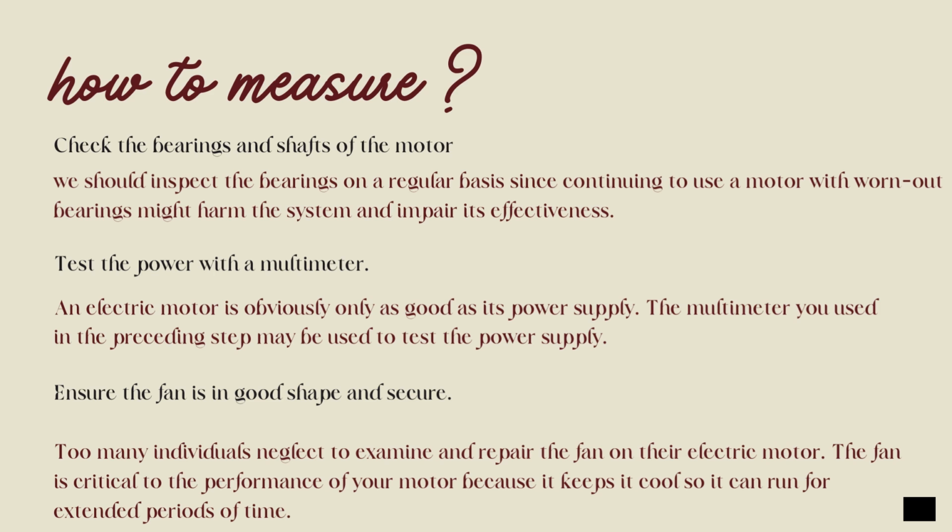The first step is to check the bearings and shafts of the motor. We should inspect the bearings on a regular basis, since continuing to use a motor with worn-out bearings might harm the system and impair its effectiveness. The second step is to test the power with a multimeter. An electric motor is only as good as its power supply. The multimeter used in the preceding step may be used to test the power supply.